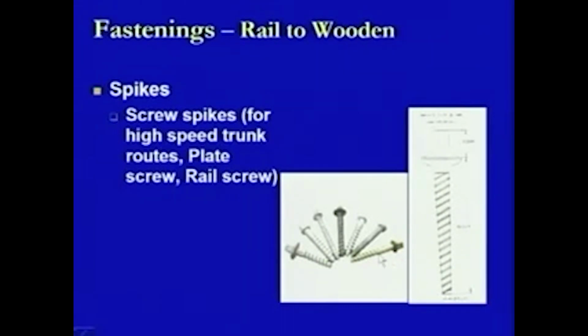Here, instead of the bolts, the only difference is that all these screws come up to the top of this one, so that when it is inserted inside, then through this hole it will get connected to the topmost surface of the rail section, and still it will maintain tightly the fitting of that rail section with the wooden sleeper. So, there will not be any loosening effect because of this much amount of screwing being provided.